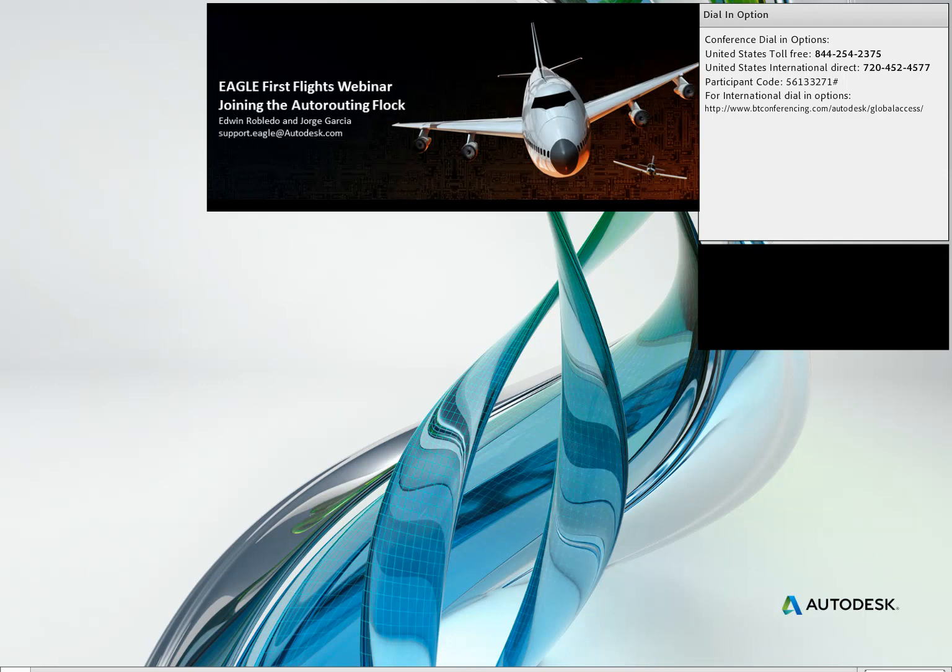Today we're going to be talking about the Autorouter. The Autorouter is quite dependent on multiple areas of the environment within Autodesk Eagle. Primarily it's going to be in regards to your design rule checks, as well as being fully tied to whatever net class settings you have defined, either on the schematic or directly on the board.